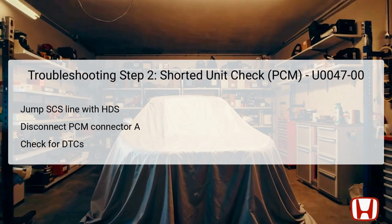Following this, you'll need to disconnect PCM connector A, which typically houses numerous vital wires responsible for engine management and control functions. After disconnecting, exit the SCS mode and power up the vehicle again to clear the DTC using the HDS. Wait 6 seconds before checking for any persistent DTC.